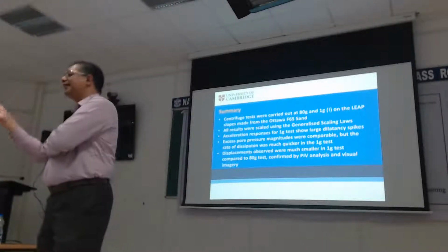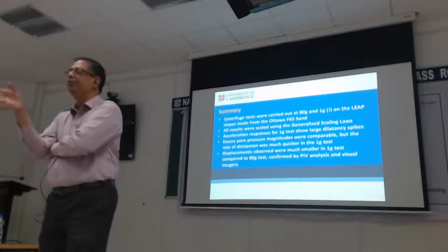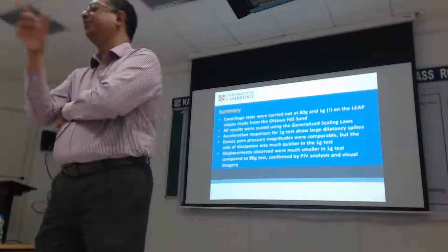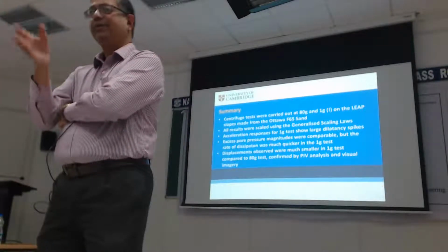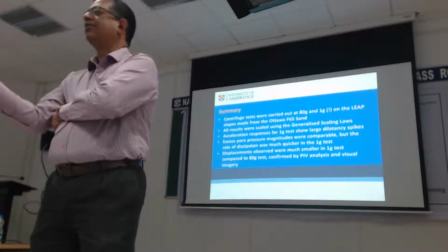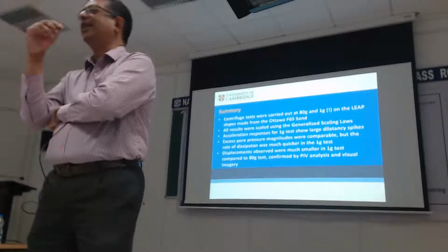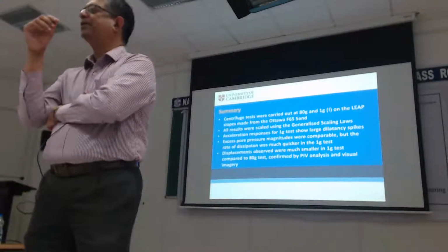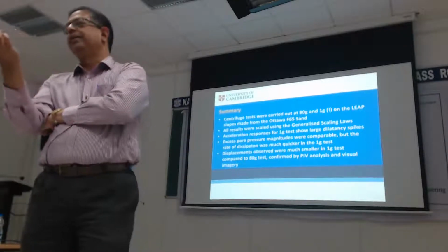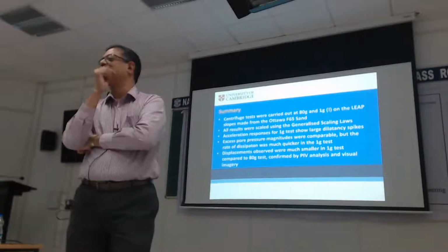If it is to do with, say, dynamic interaction between pile and the soil, by all means, then the important thing you should get right is the relative stiffness between the pile and the soil. Get that right, even in a 1G. Then you can compare with several 1G tests. As long as you then don't say that, oh, the Kobe piles are going to behave this way in reality, everybody's happy. And that's a useful contribution as well, as I see it. It's just overreaching to the far right that is the problem.